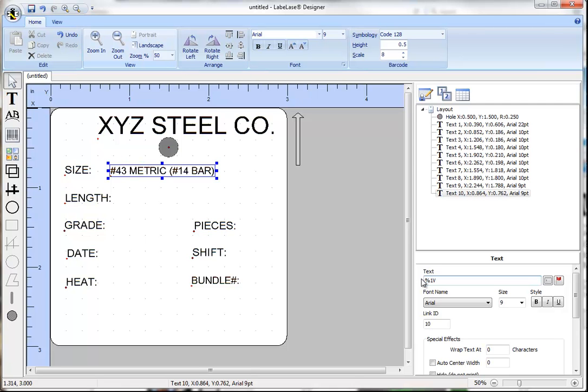%1V. The percent character tells Producer that what follows is a special flag. The 1V indicates the first entry in the operator data entry table. Many such flags allow you to insert automatically generated or numerically sequenced data. Select a font size of 12 for this text to help distinguish it from its corresponding label. This is purely individual preference, but it makes it easier to differentiate the data from the labels.